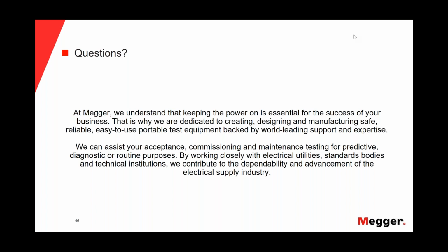Additionally, what special PM testing and type of equipment would you recommend for low voltage or 600 volt feeder cables in operation for over 15 years? When you say 600 volt low voltage cable, there is a certain issue with it because they're normally unshielded cables. And when I have an unshielded cable, then I have a problem doing basically any type of test because I cannot establish a defined test potential or a dielectric